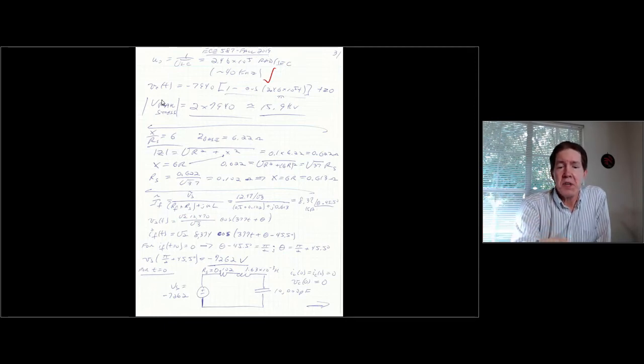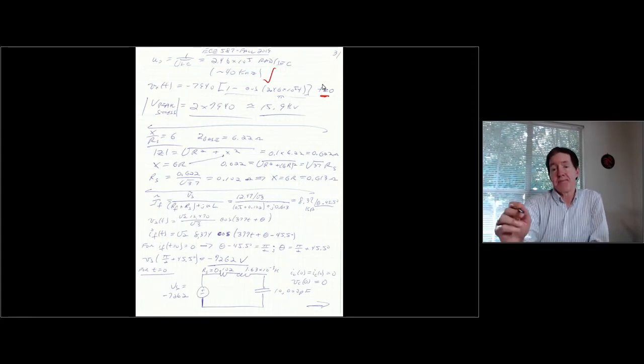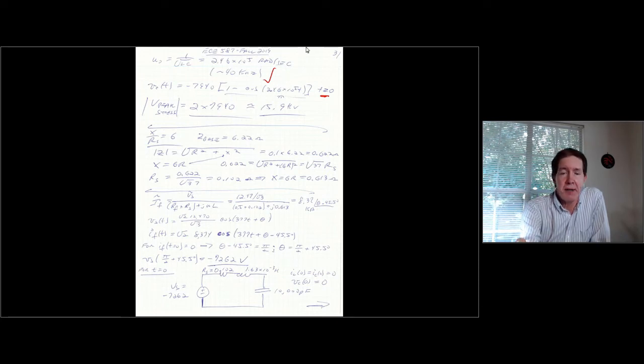And then the form of the voltage is going to be equal to minus 7,940 times the quantity of 1 minus a cosine of this resonant frequency times t, for time greater than 0 when the fault was cleared. So what's the peak stress on the circuit? Basically, that's going to occur when the cosine term is minus 1, when omega naught t is equal to pi. And in this case, if you just look at the magnitude, it is 15.2.